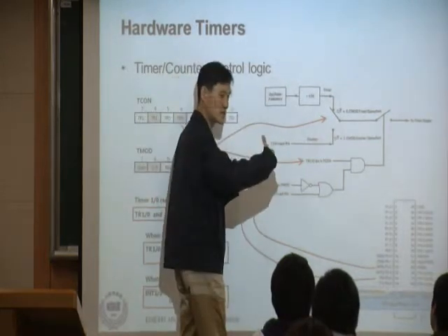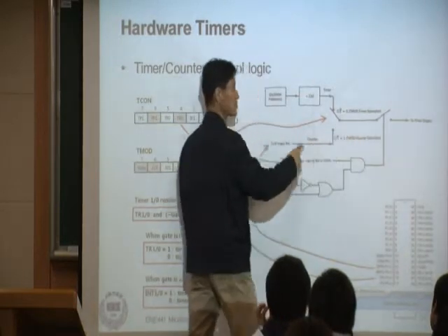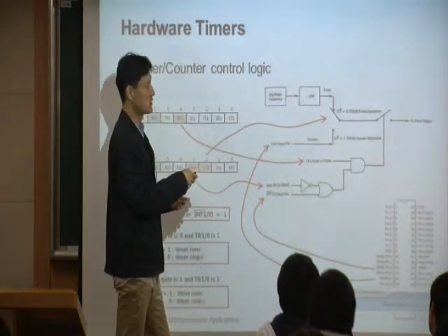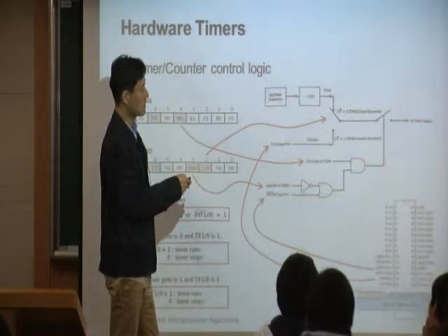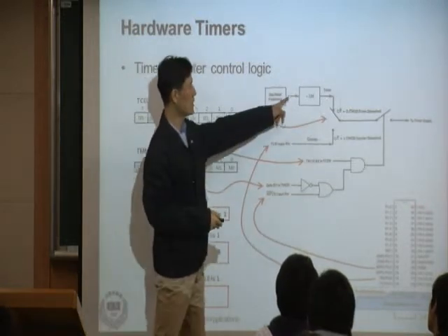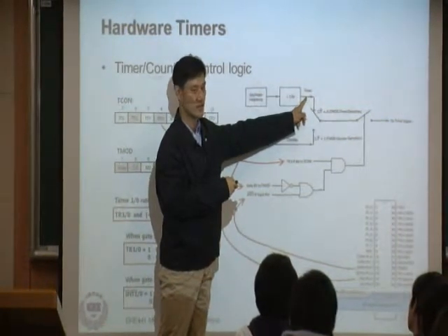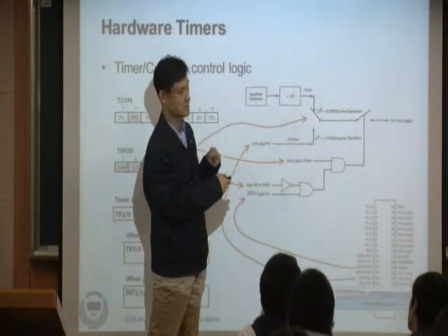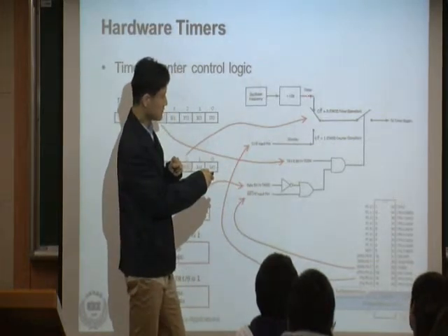And this one actually generates clocks. And clocks look like this, a rectangular pulse, right? So you are going to get the rectangular pulse here, and that rectangular pulse has the frequency of 12 megahertz. Now that 12 megahertz clock, you're going to divide by 12. So here it was 12 megahertz, but 12 divided by 12, right here, it's going to be a 1 megahertz clock. Right here, that is the input 1. That's the input to your timer hardware. Okay, 1 megahertz clock.